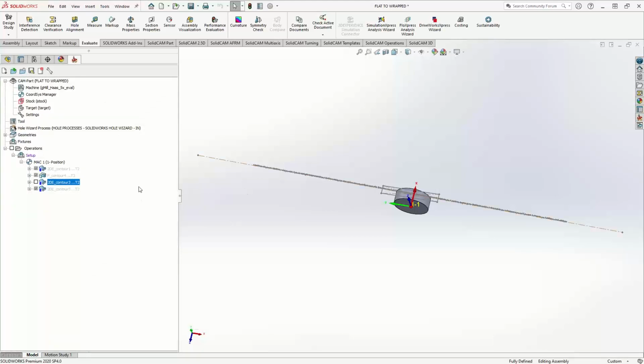Okay, so any questions on wrapped engraving, wrapped geometry, multiple depths, anything like that? The only thing you can't do with depths in wrapped is progressive depth. That's probably something you need your multi-axis toolpath for, something like fourth axis simultaneous, because then you can actually choose a line or a feature that progressively moves down, maybe like a cone shape. Wrap geometry is only for fully concentric features or things that can be fully wrapped around a common center.